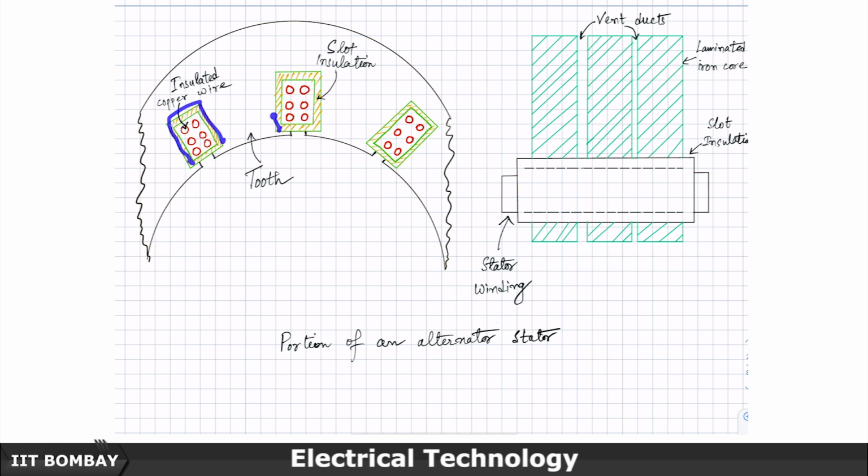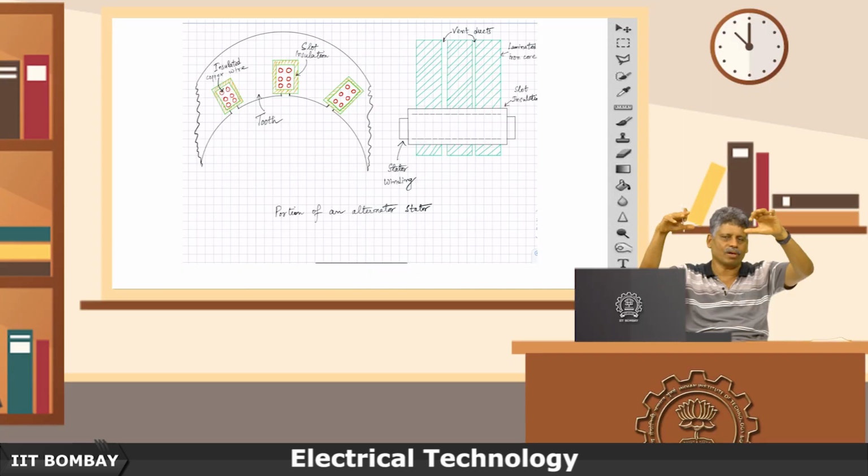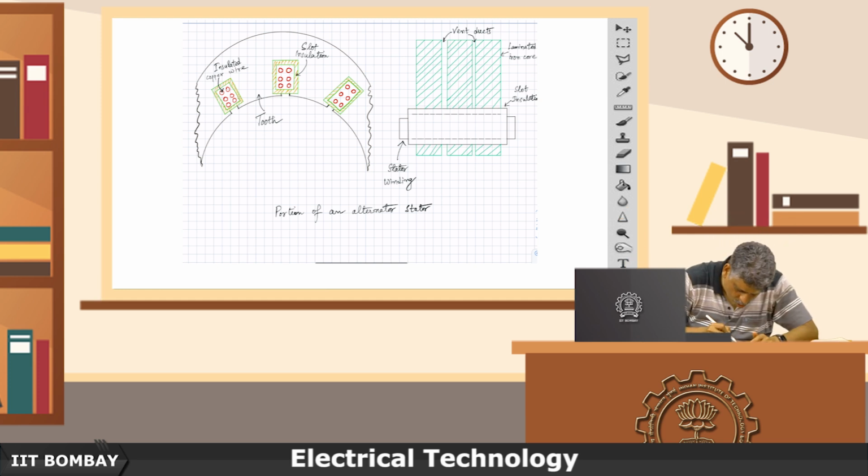or gaps in which you are having this insulated copper wire conductors. If it was just kept open like this, then suddenly a lot of air gap, then again iron coming up, again a lot of air gap. So, the magnetic flux distribution around here would be much more haywire, and therefore, you would have a lot of ripples happening. Hence, it is almost enclosed.